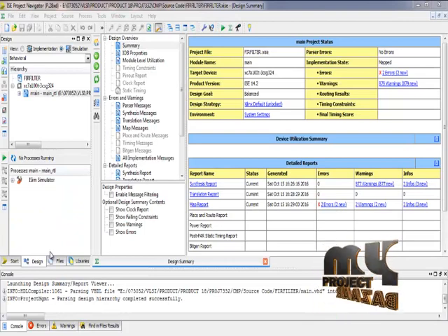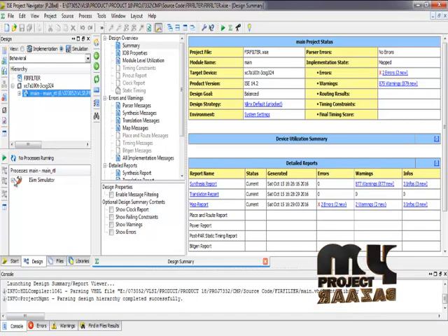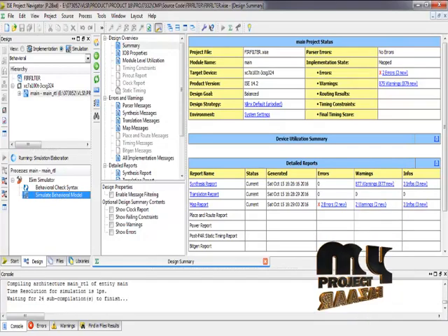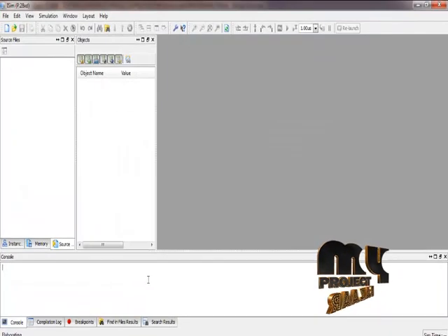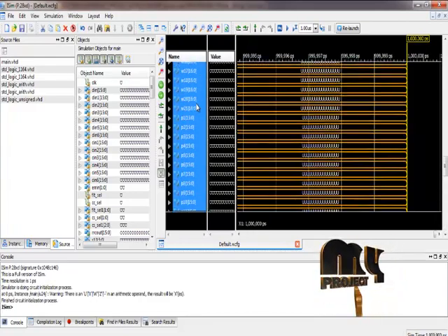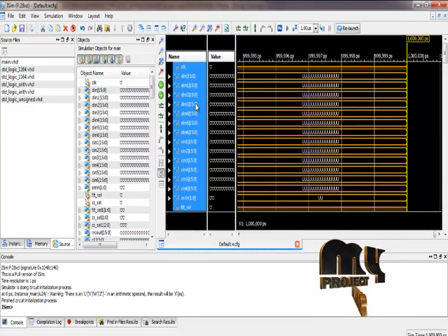Now we will discuss our process running procedure. We have designed our FIR filter in the Xilinx 14.2 version tool, and then run the power simulation process. After we click simulate behavioral model, we get the output in the ISim process. The simulate behavioral model finished successfully and the ISim simulator opens automatically. In the process we give the input for the clock and DIN, and then get the output for the RRC output in the FIR filter.